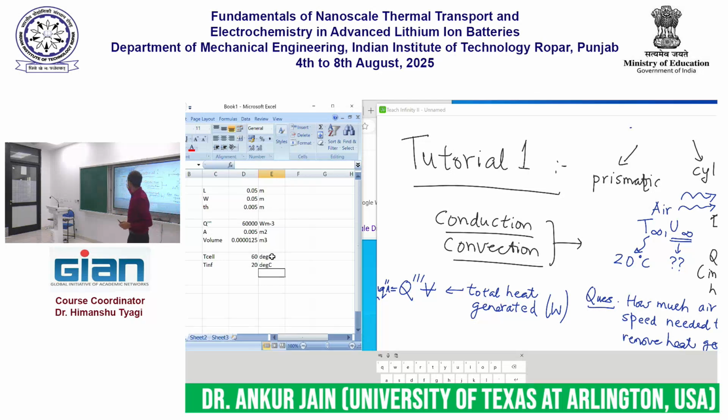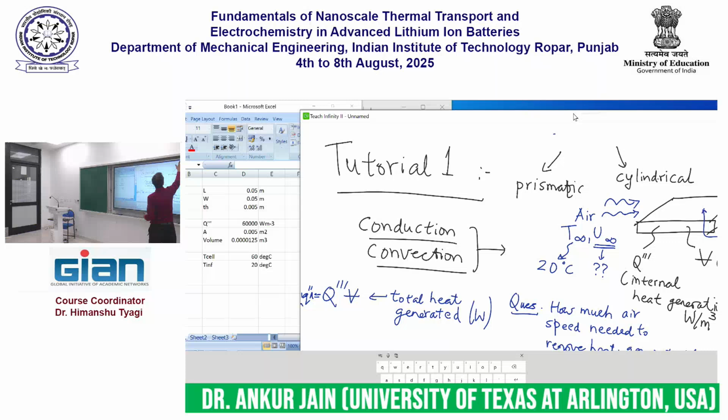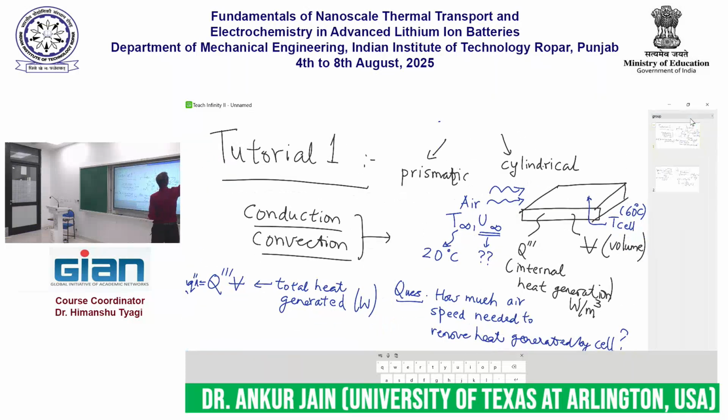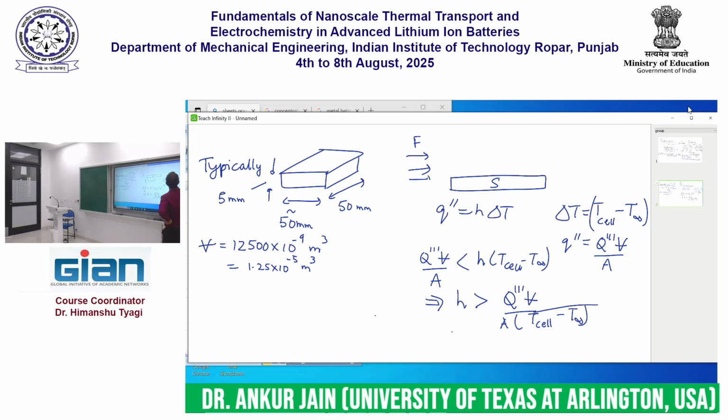The advantage of doing this Excel thing is that now I can do my calculations very fast. Having entered all the numbers, the calculations are easy and I can go back and change these numbers as I go through my design process, right? So let's look at the equation we had. Q triple prime V over A times T cell minus T infinity.